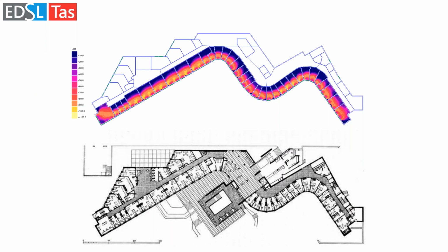for a fixed time and day. Here, moving to show one floor plan from that building being analyzed, instead of just a couple of rooms being analyzed for daylight, we're moving up to a climate-based daylight modeling approach where multiple hours through the year are analyzed. We do analyze the whole year when we do CBDM analysis, and in this case we even reduce the grid spacing to 10 centimeters, or a third of a foot square, so much less than is needed for LEED, just to get a super granular grid to see what was going on, and also to test the software out for its performance. But again, this is just so you can review that in the context of an entire floor for the project.